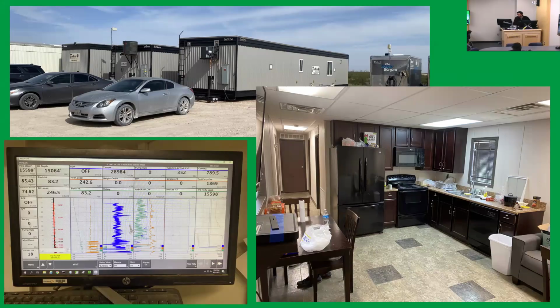This is the screen that everybody shares. Hole depth is how deep the hole is. Bit depth is where the bit is standing. Notice that the bit is standing about 500 feet above the hole. You know why? ROP is off, we are not drilling. Torque is high, that means we are rotating. Hook load is okay. Block height is basically how high the traveling block is. It's at 83.2 feet. It can go as high as 100.